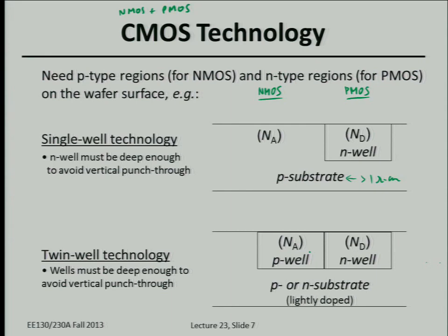Okay, let's review. In a CMOS technology, what would be the typical bias of the P-type region, the P substrate? It's either 0 or the supply voltage. Which one? For the P-type substrate, you would ground it. And for the N-well, you'd maybe have a little contact, some metal, and that would be biased at VDD. N-type regions are usually biased at the highest possible voltage, so you'll never get a forward bias p-n junction to cause current to flow into and out of that well.